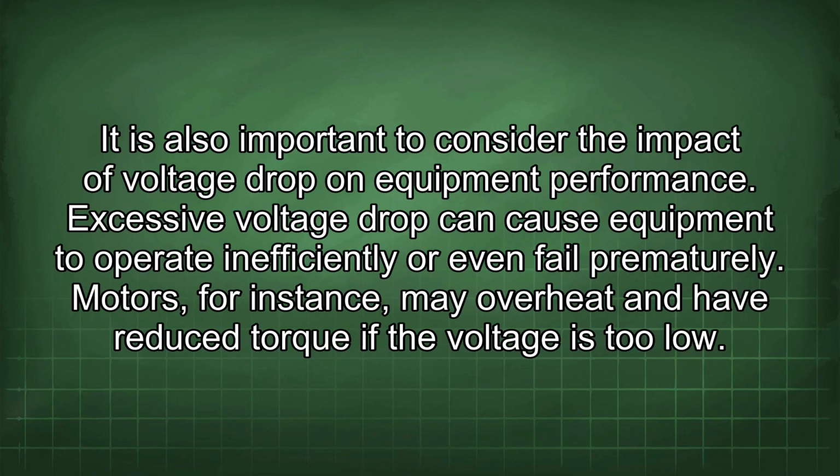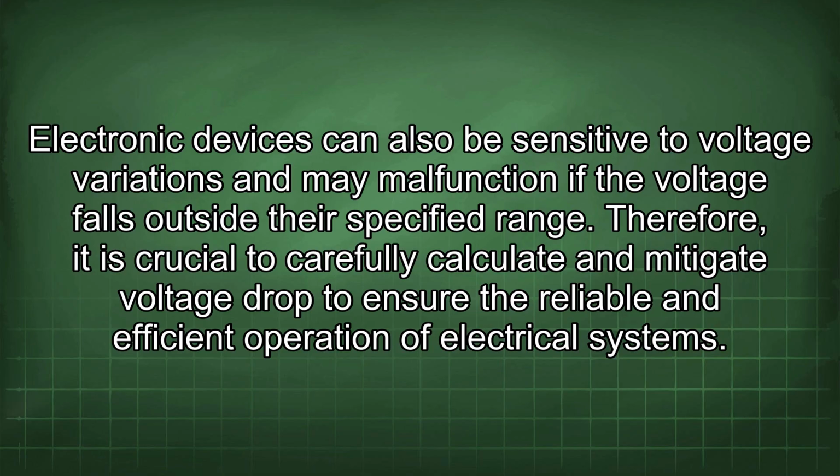It is also important to consider the impact of voltage drop on equipment performance. Excessive voltage drop can cause equipment to operate inefficiently or even fail prematurely. Motors, for instance, may overheat and have reduced torque if the voltage is too low. Electronic devices can also be sensitive to voltage variations and may malfunction if the voltage falls outside their specified range. Therefore, it is crucial to carefully calculate and mitigate voltage drop to ensure the reliable and efficient operation of electrical